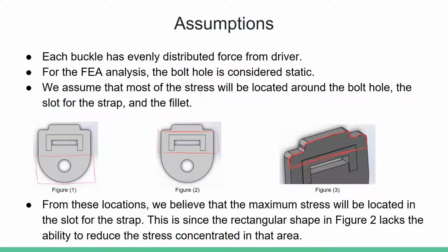From these locations, we believe that the maximum stress will be located in the slot for the strap. This is since the rectangular shape in figure 2 lacks the ability to reduce the stress concentrated in that area.